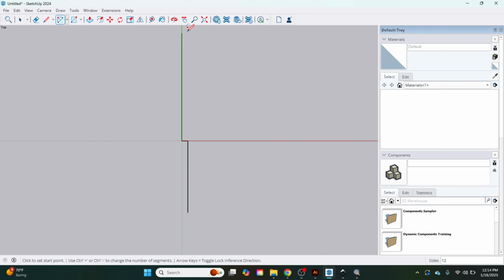Here's the arc tool. All I do is this little green dot shows you that it's the end point. You're going to go down to the other end point. And then look, the bulge. And look, I know I want to stay within 6 inches. And if you look here, just so you know, it's measuring from the middle of this. So it's actually, if this is 2 inches, it's measuring 1 inch in. So if I want from here to the very end to be 6 inches, I need to subtract an inch. So what I'm going to do is type in 4.75.